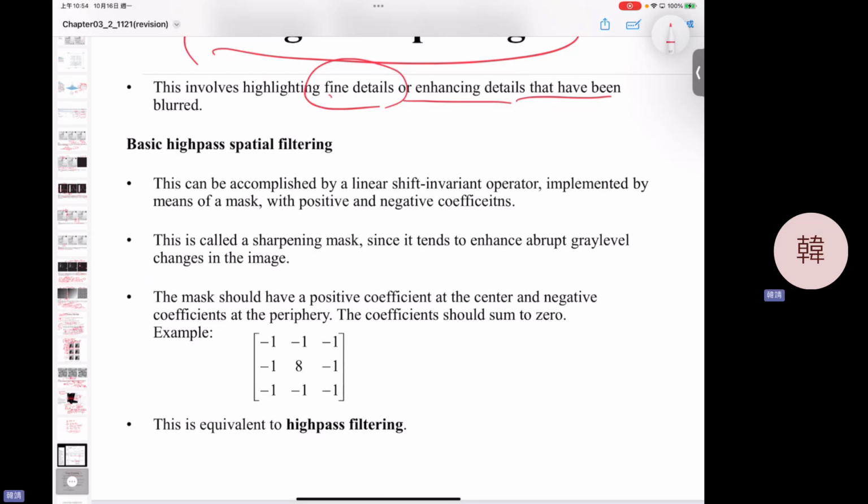If you look at the Gaussian filter, a low-pass filter, again the coefficients are all positive, right? All the same sign there. However, if your mask includes some positive numbers and some negative numbers, it acts as a difference operation or derivative operation in the filtering. Which means you are going to take some high-pass band information from your image.